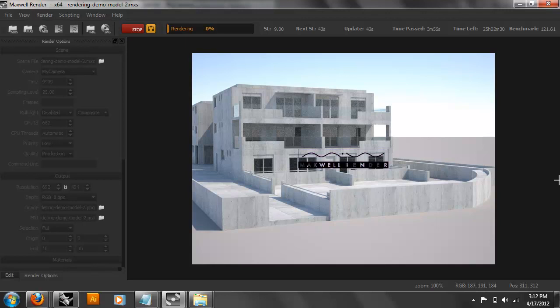The better your model, the better the result, and there are little bits, guys. If you look at the corner of the building, some of these things are a reveal of bad modeling. If your stuff is not joined well, if you didn't snap things well, if things are not in alignment with each other, it's going to show up as a little shadow artifact, a little catch of light you don't want. So a clean model is going to be a clean render.